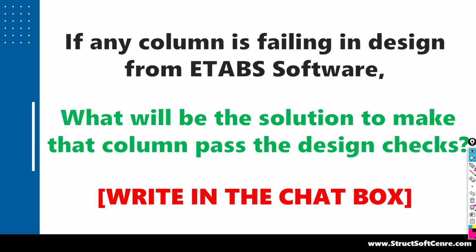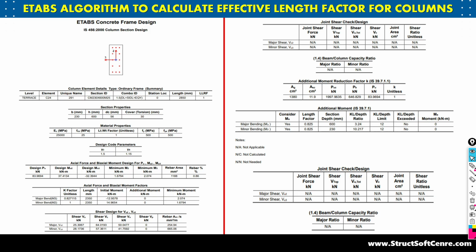You are not going to diagnose the problem, and without diagnosing the problem you are giving the solution. This is the important thing. So how can you diagnose the problem, how will you come to know what the actual cause of the failure is? Either your column is going to fail in axial load, in flexure, or in shear. Or it is going to fail due to the sectional, meaning geometrical, failure, meaning short column or long column effect. What is the cause of failure? That you need to know.